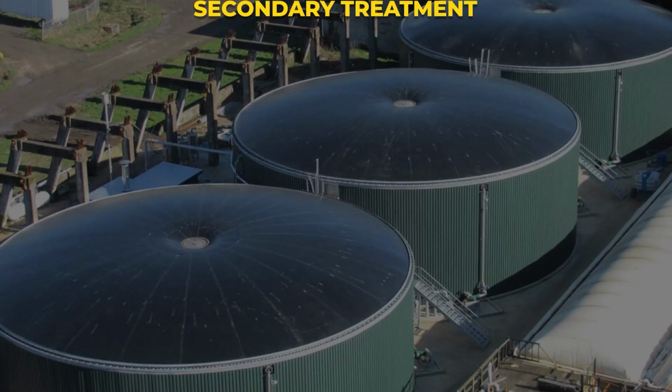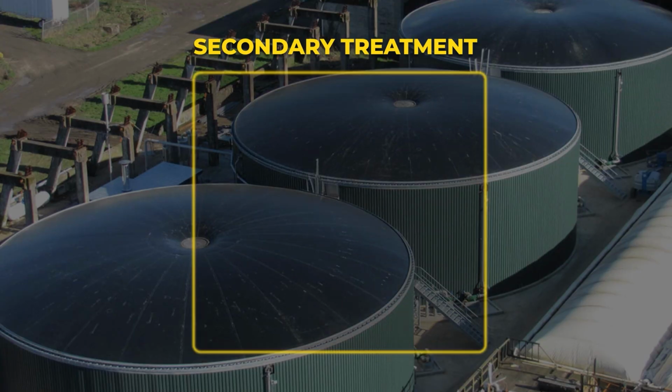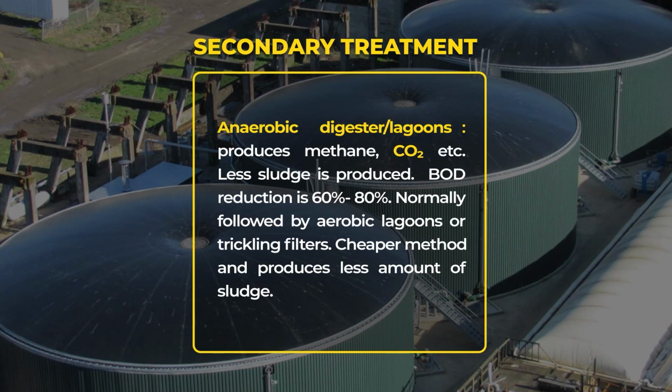After the primary treatment, the treated wastewater is sent for secondary treatment, where microorganisms help in decomposition of the organic and inorganic components present in the wastewater. Secondary treatment can be anaerobic or aerobic. First, we will see the anaerobic digestion of the organic components. Anaerobic digesters or lagoons produce methane, carbon dioxide gas, etc. But they produce less sludge, and the BOD reduction is almost 60 to 80%, and normally it is followed by aerobic lagoons or trickling filters. It is a cheaper method and it produces less sludge.